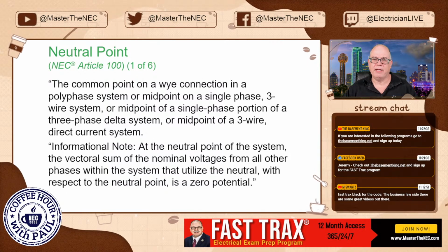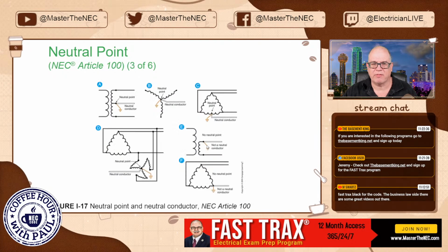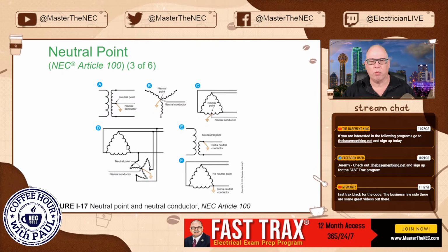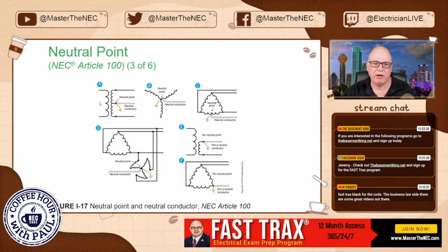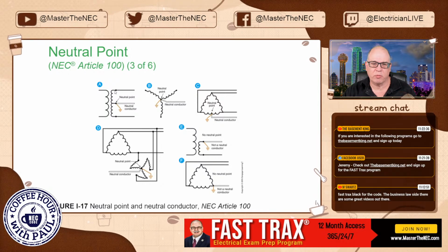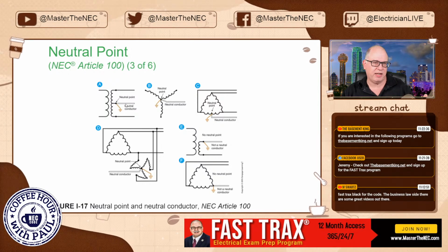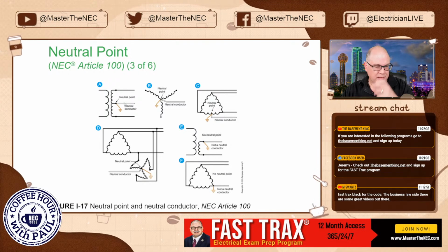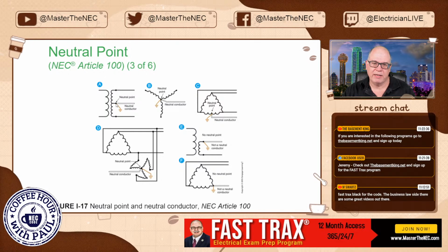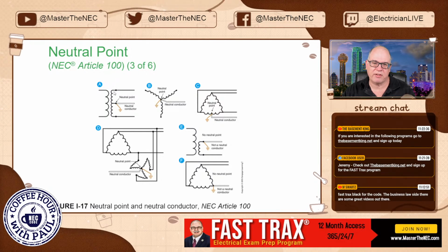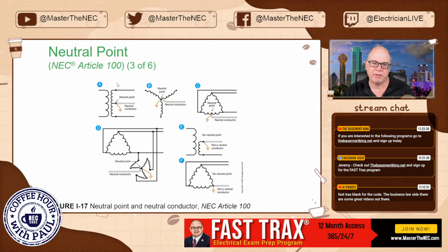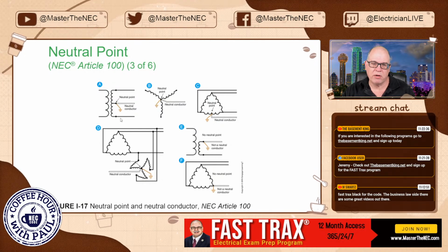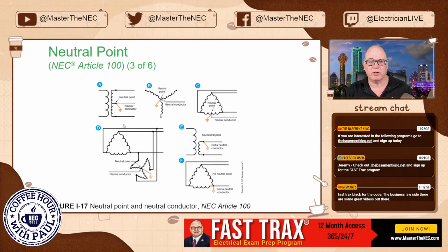Neutral point is, if you take, and I might have a picture to make this easier. So here's a neutral point. If you ever wondered what this definition is, so here's a system right here. This is the neutral point. So this is basically what you probably see at a residential: 2 hot legs and a neutral shared, okay? And here, your neutral point right there is where that neutral conductor connects, and it's 240 between them, or 120 equal to this neutral. So it's a neutral conductor.